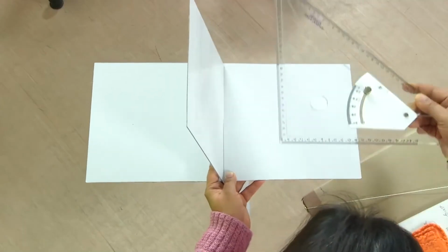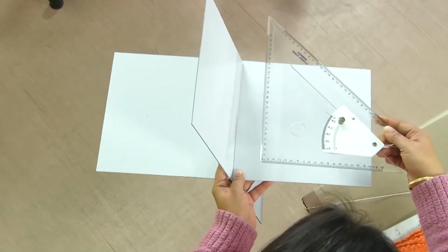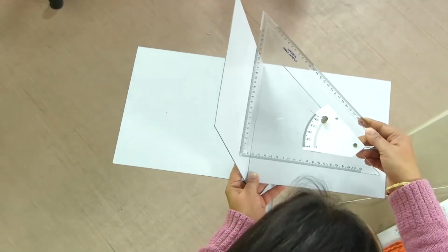We see that the line which we got as a projection on VP, which is the vertical trace, is now inclined but it remains the same length, and the horizontal trace, the HT, is not the true shape anymore because it is not parallel to HP anymore. So we will have a diminished, slightly reduced size which will be seen in the HP.